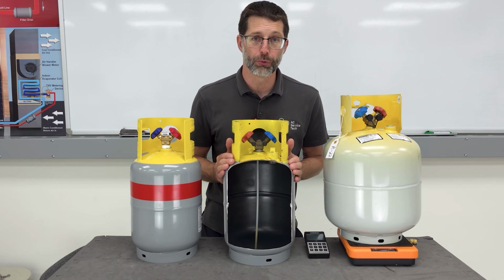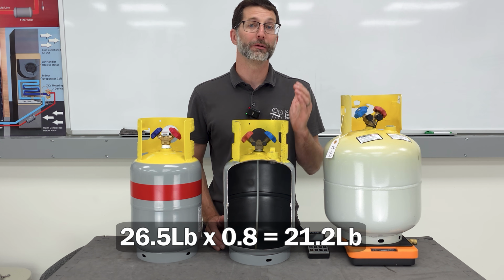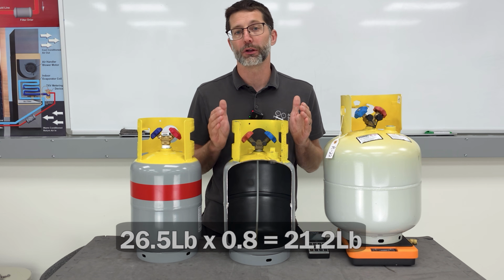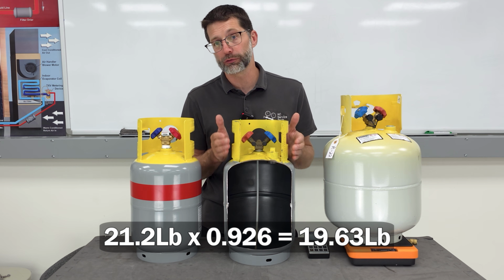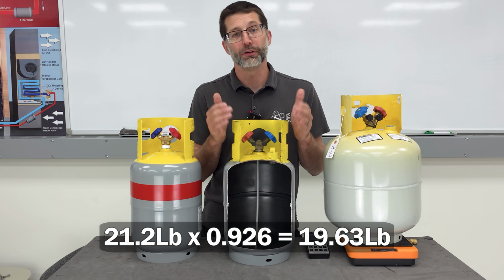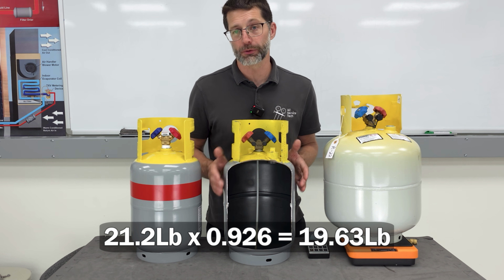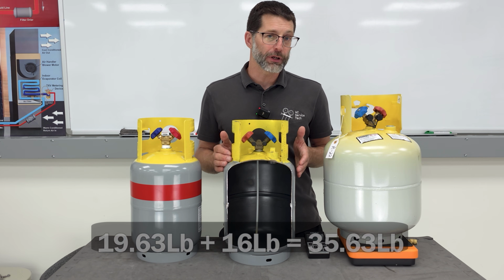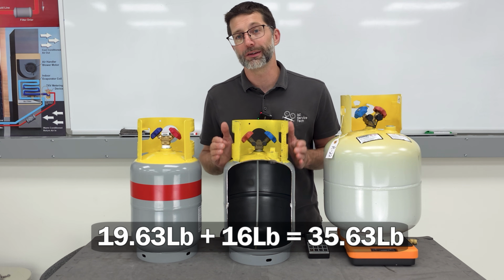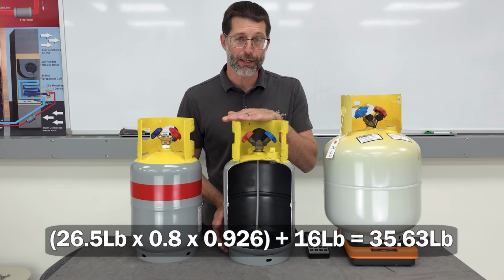So let's go step by step through this. So we got a water capacity of 26.5. We multiply that by 0.8, and so that equals 21.2. Take 21.2 times the specific gravity of R-410A at 120 degrees, and so that's 21.2 times 0.926, and so we equal 19.63. So then we take 19.63 plus the tare weight, which is 16 pounds, and we equal 35.63. So that's the amount of pounds as your max weight that you should have.